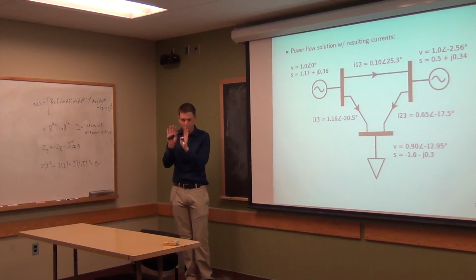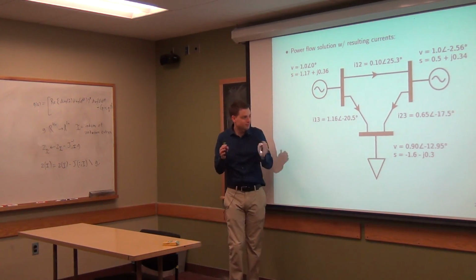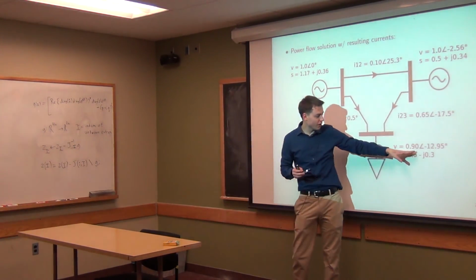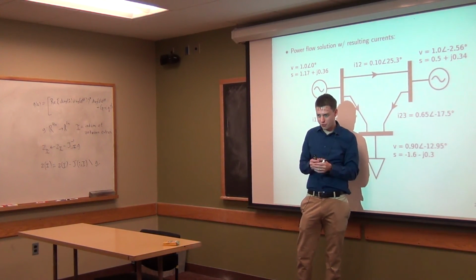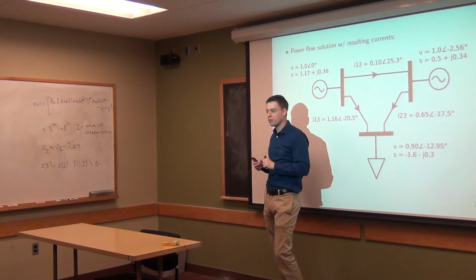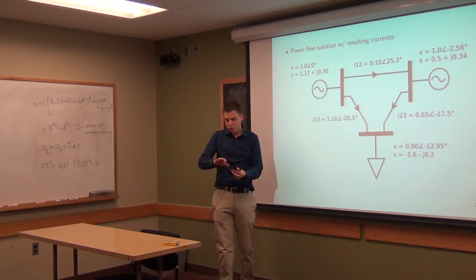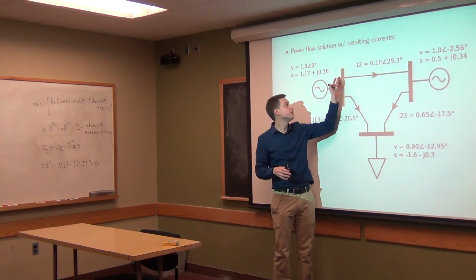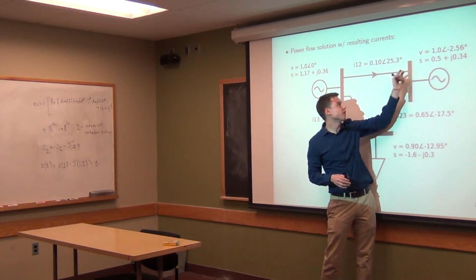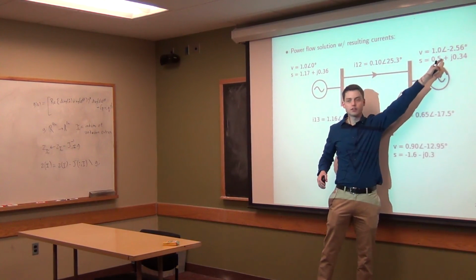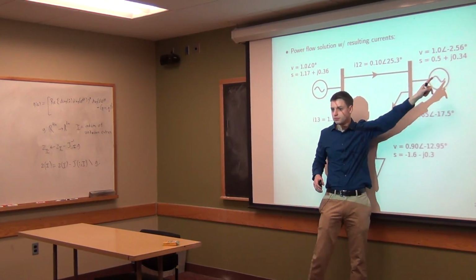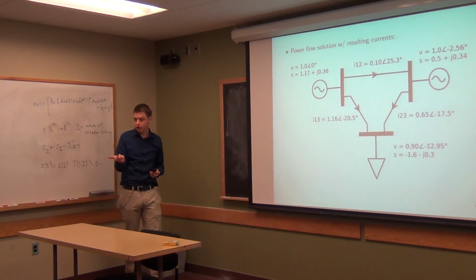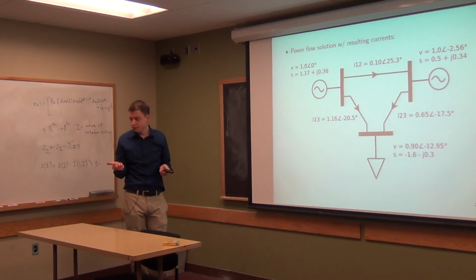Don't worry about it too much, but actually do think about it, when there's both. If there was a case where one was higher than the other and the other was lower, there would be a trade-off, of course. But typically, in general, you will find the solution and then current will flow in these directions from higher voltage. So these voltages are the same, for example, but current is flowing because the voltage angle is lower here. So current can flow for either of those two reasons, right? It can flow either from different voltages or from different phase angles.